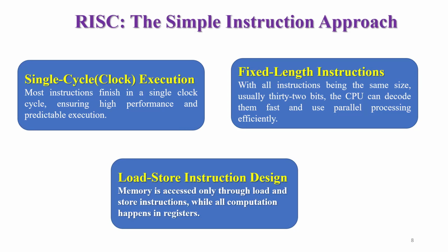So RISC architectures have their own set of advantages. Instructions finish in one clock cycle, making performance predictable. Then all instructions are of the same length. And this simplifies decoding and allows efficient processing or pipelining.